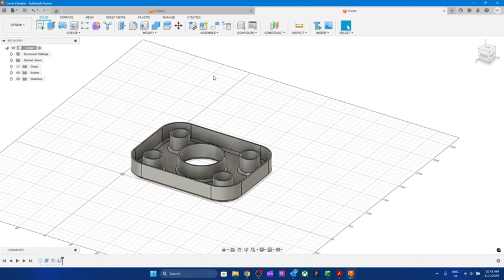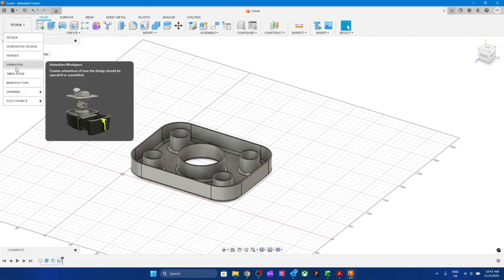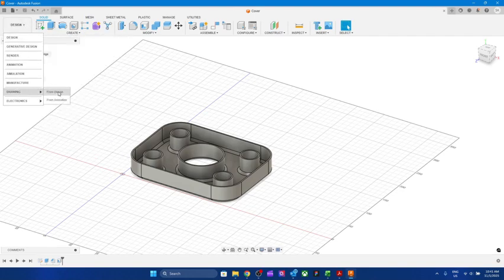Every product that you make or design, it requires the 2D drawing. Okay, so in this case I will show you how to do the 2D drawing. So once you have saved the part, everybody save the part as cover. Okay, now save the part, and then you can go into drawing from design.